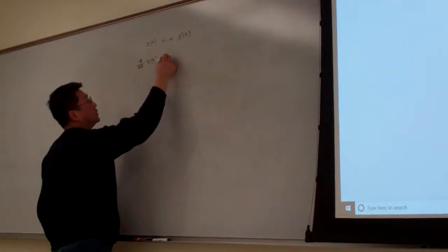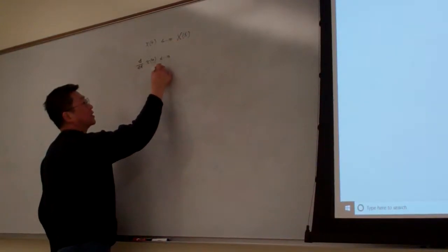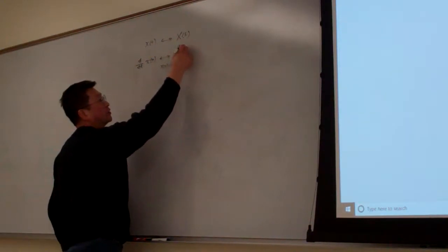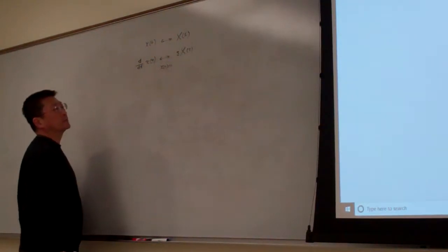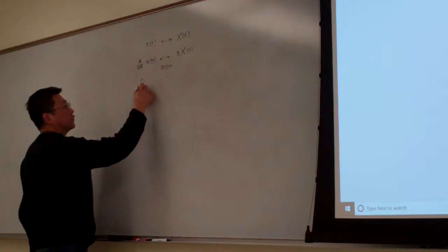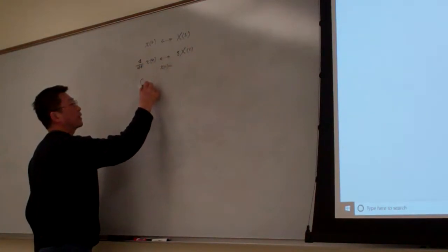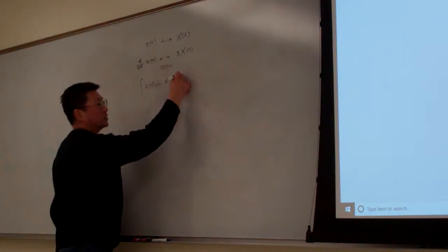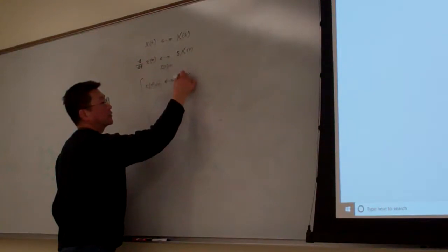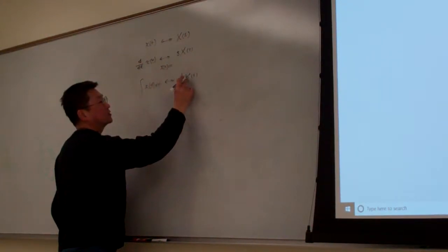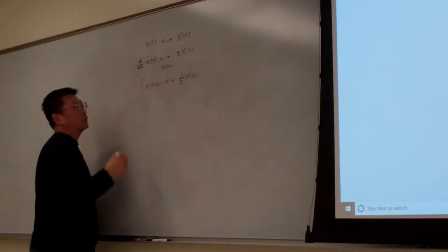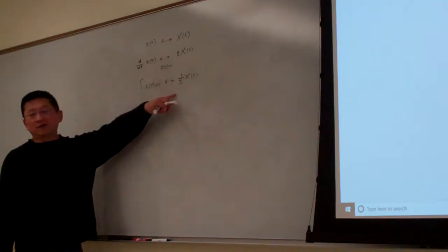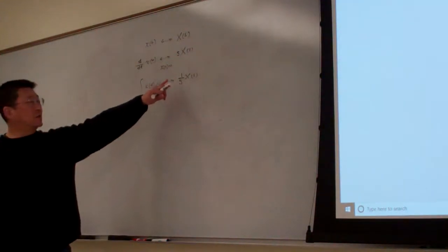If we let the initial conditions equal 0, then the transform is simply s multiplied by capital X. And if we have an integral of x of t dt, then the Laplace transform is simply 1 divided by s times capital X. So for a derivative, we simply multiply by s. For an integral, we simply multiply by 1 divided by s. Keep this in mind.